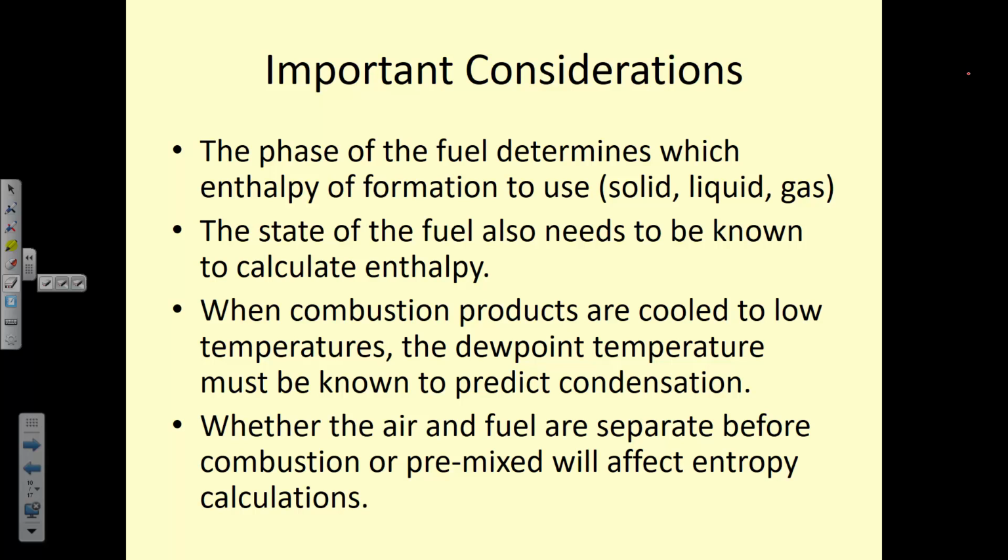What's really fun is when we start dealing with humid air. So now we worry about the fuel coming in, but also now we have to worry about that there's some moisture in the air as well, and we'll do an example of that today. And that's important because when we cool these combustion byproducts down to low temperatures, some of them may precipitate out. So water might liquefy. We might have water in our products in the liquid form, whereas maybe it was in the vapor form in our reactants. So again, it's a different enthalpy term if it's a liquid versus a vapor.